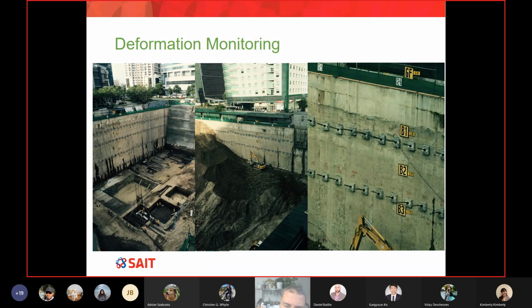We measure the coordinates today. We call this the initial measurement, and we measure them every day. And we reference our measurement on one day to the first day. This is what will give us the change in coordinates, and that will give us the deformation.